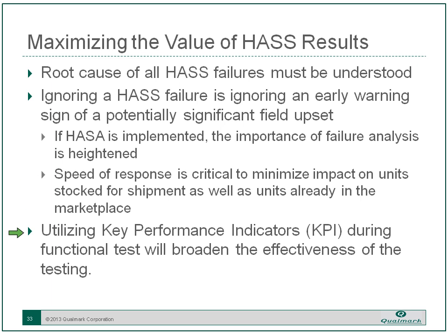Now, one thing we've talked about a few times before, I haven't mentioned today so far, is the idea of key performance indicators. These are used like prognostics are used for indicating wear in the field. If you have found during HALT that there are parameters to monitor during functional test that can indicate a tendency to failure or a potential for failure, like noise on a line or timing getting close, or some other performance indicator that lets you know this unit is starting to behave poorly, it's not quite failed, but it's starting to behave poorly.